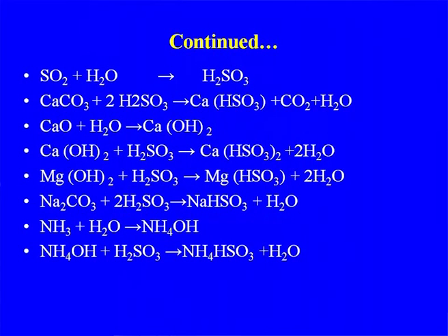After that, looking at the problems inherent in sulphite pulping, we went for kraft pulping, because the quality of the paper was better in case of kraft pulping, plus the pollution point of view. So, this was the problem in sulphite pulping, and so we are not using sulphite pulping anywhere, but let us discuss in brief about the bisulphite that we are using.